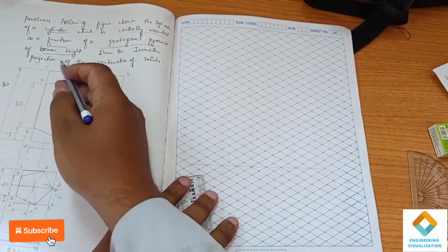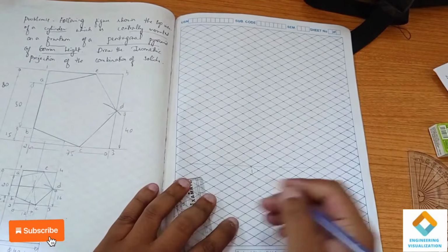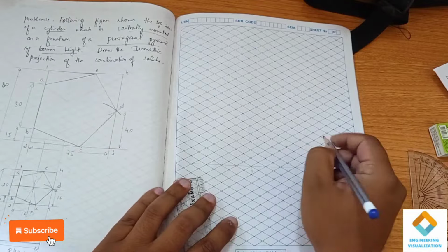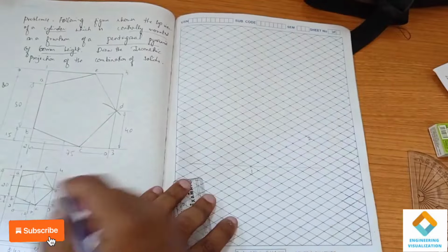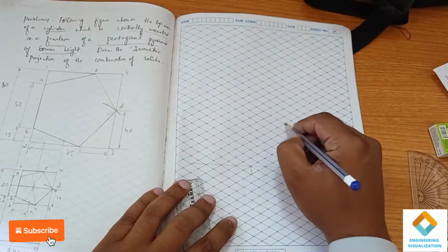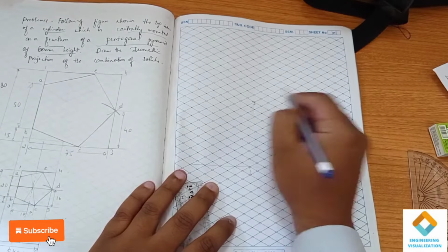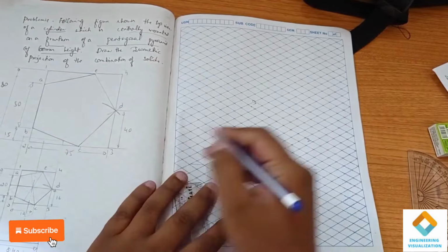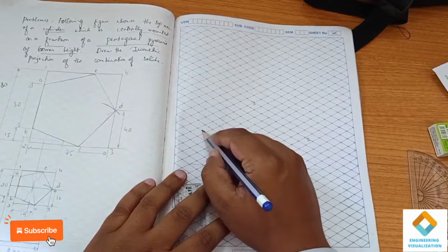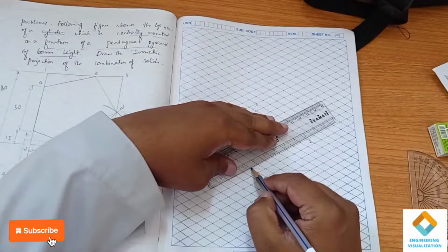Okay, so say this is our reference point. Say here first I will construct this from 1. You can see that from 1 to 2 we have 80. 80 means 8 boxes. 2, 3, 4, 5, 6, 7, 8. Okay, then this point is 2. 2 to 3 we have 75. 75 means 7.5 boxes. 1, 2, 3, 4, 5, 6, 7, 7.5. Then this point is 3. Again from 3 to 4 it is 80. 80 means again 1, 2, 3, 4, 5, 6, 7, 8. Okay, so this point is 4. So now we are going to join.